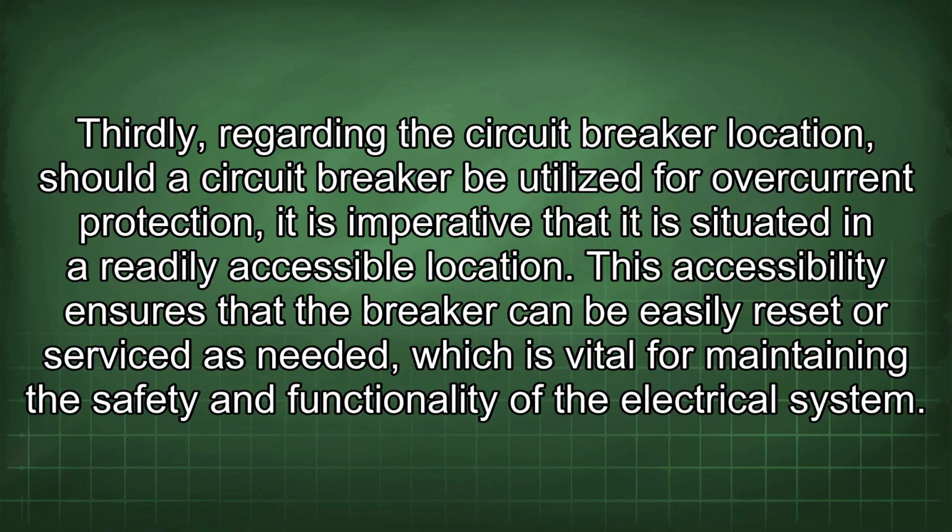Thirdly, regarding the circuit breaker location, should a circuit breaker be utilized for overcurrent protection, it is imperative that it is situated in a readily accessible location. This accessibility ensures that the breaker can be easily reset or serviced as needed, which is vital for maintaining the safety and functionality of the electrical system.